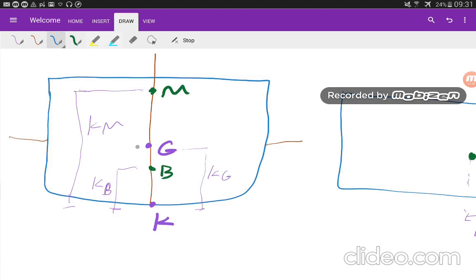We have a downward force from our center of gravity, and an upward force applied by the water to the vessel from the center of buoyancy, and these two forces must be equal to keep the vessel afloat. So displacement is the force applied by gravity, and buoyancy is the force applied by the water to the vessel. These two are equal.